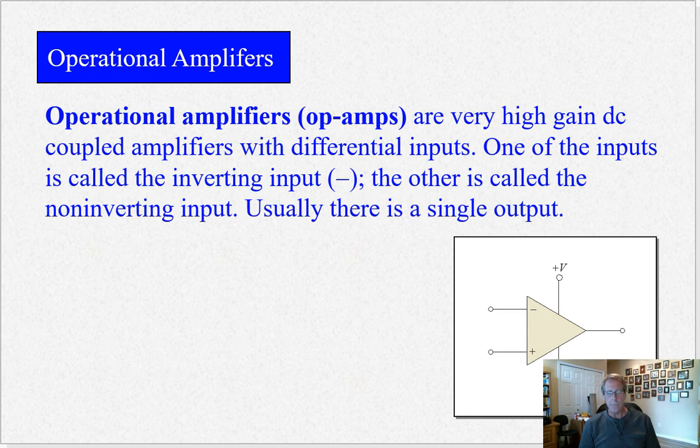here. But today we're just going to look at the basics of the operational amplifier with no parts around it, just what makes the inside of it work, or what the basic concepts of it are. So here's a schematic symbol of an operational amplifier. It has two inputs, a negative input or inverting input and a non-inverting input. And then most operational amplifiers have one output. Some of them have two, but for now we're just going to look at the ones with one output.